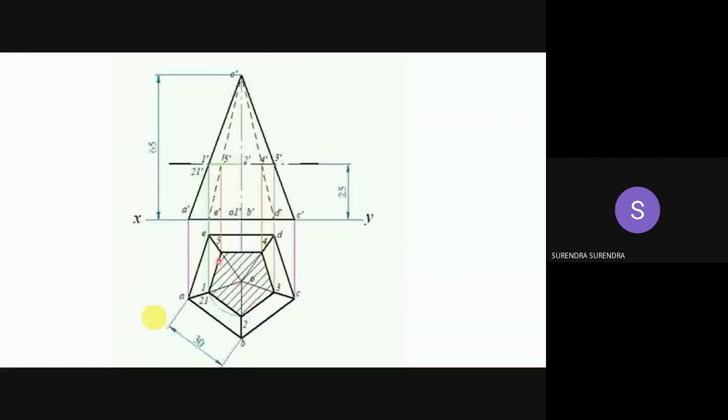These lines must be parallel to each other and equidistant, and maintain the line-to-line distance of 3 mm perfectly, so that you will get an accurate, neat shape. And as you are removing this portion, these lines are represented with 2H. Initially, draw the entire top view with a 2H pencil and only highlight the retained part.